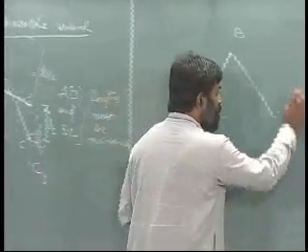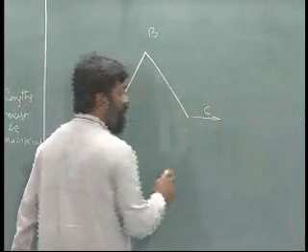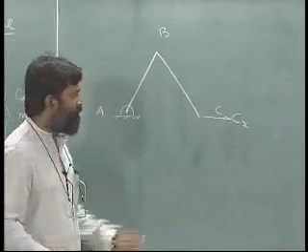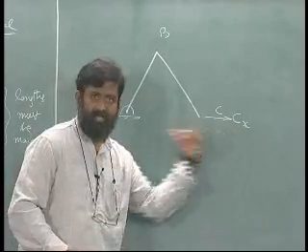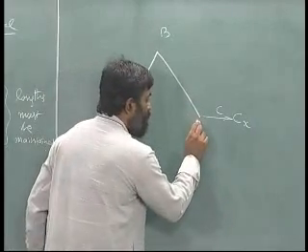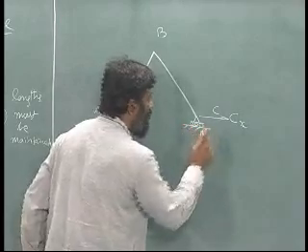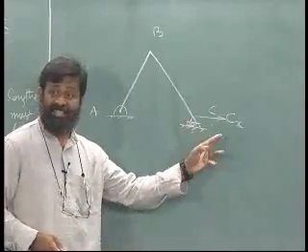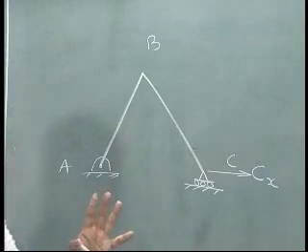Okay. So, in this particular case, let us say I am applying the reaction, let us say this is Cx. Mind you, this is a choice that I have made. If the reaction is not this way, it has to be this way, I will automatically get a negative value for this. Okay. Now, I have to free the horizontal displacement. So, now I am consistent with what it should be. Whenever I release a displacement, I have to apply the appropriate reaction to it. So, I have done the job.